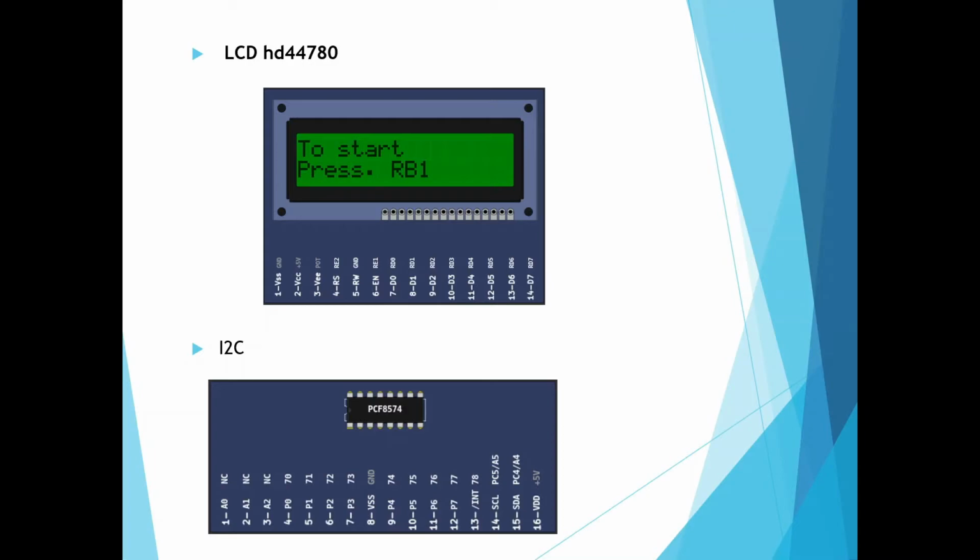We can select either the data register, which holds what goes on the screen, or an instruction register, which is where the LCD's controller looks for instructions on what to do next. A read/write pin that selects a reading mode or a writing mode.